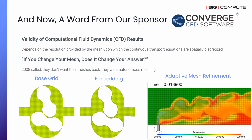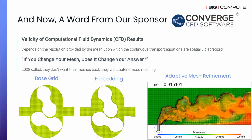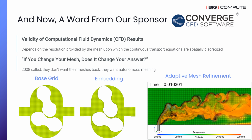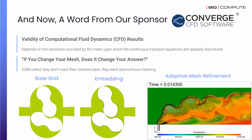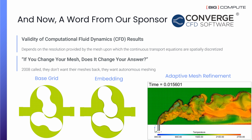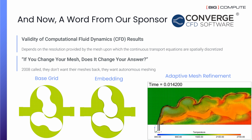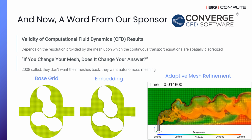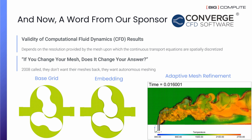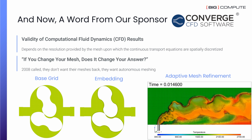So what I'm showing on the right is sort of the final step in our meshing strategy, which is known as adaptive mesh refinement, where the solver itself calculates on the fly how much mesh should I add and where should I add it. So what I'm showing here is a jet in crossflow, and you can see the gradients are leading to the code adding more cells to capture those gradients in a dynamic way. If we were to try and capture this with a uniform mesh, we would have a far greater number of cells than we have with this adaptive mesh refinement. So this is a way for us to basically guarantee that we get the maximum accuracy for the minimum cell count cost.